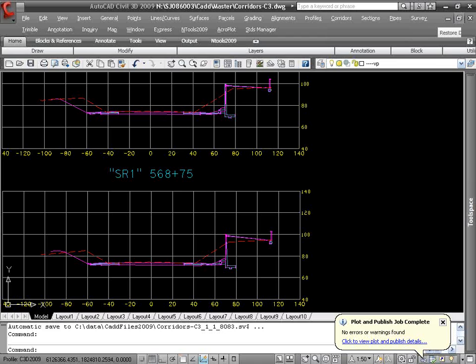But overall, I'm pretty impressed with the model they built. Lots of lessons learned, especially in terms of being able to see that entire roadway in a single section view. I think that's the big thing Brandon came up with: do that single baseline and just have those assembly offsets in here to build these complex corridor models.